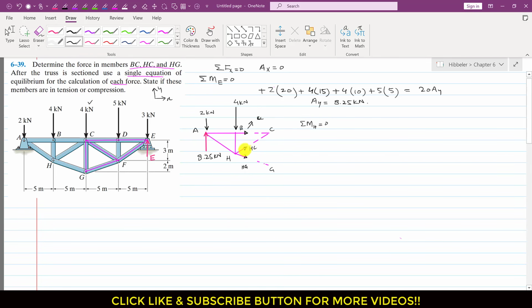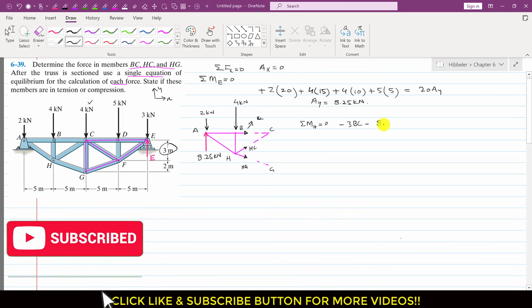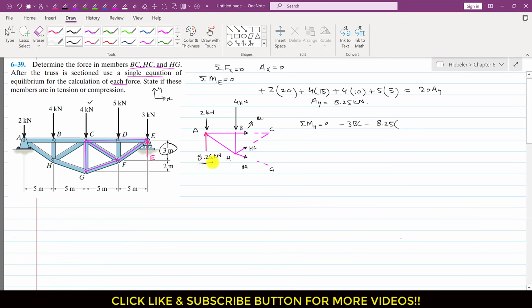Now as we can see, if I apply the summation of moment about point H, this BC is producing a clockwise moment about that point H, so I will write minus BC, and the perpendicular distance of this BC force from point H is the length of this BH member, which is 3 meters. So I have to multiply it with 3, right? Similarly, this 8.25 kilonewton force is producing a clockwise moment about point H as well, so I will write minus 8.25, and the perpendicular distance of this force from point H is the length of this EB, which is 5 meters, so I will multiply it with 5.